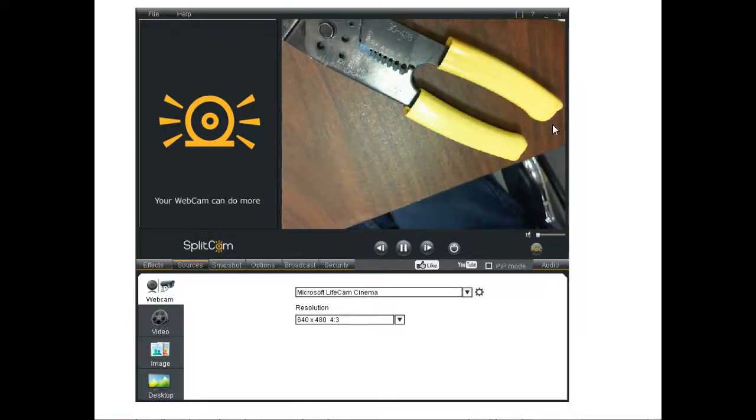So what you need to do is dry fit it, right? Of course, over time you'll learn the lengths, and I think I give you the lengths. But you'll learn it over time if you do a bunch of these. But to start off with, you need to strip it, you need to twist it together real good, and you need to put it in there. And if that insulation doesn't go up into that insulation just a little bit, you don't have to do very much, right? You understand that? Then you need to clip it off a little bit. Right? That makes sense?